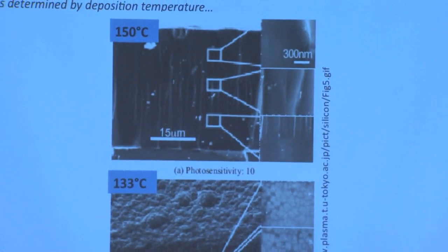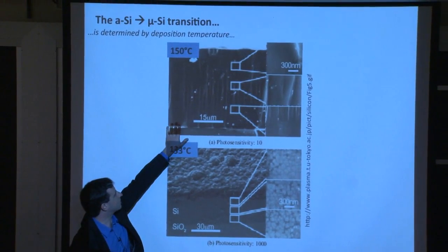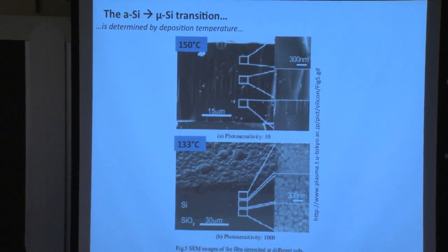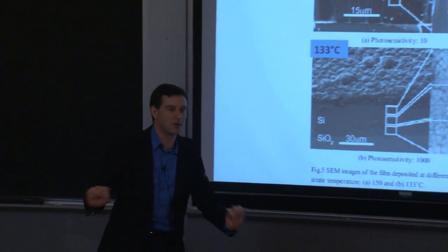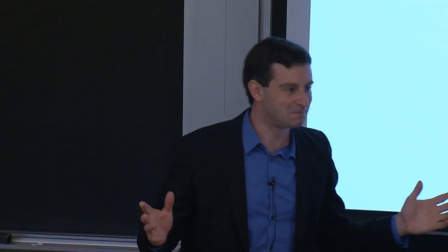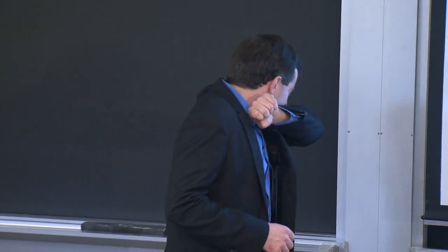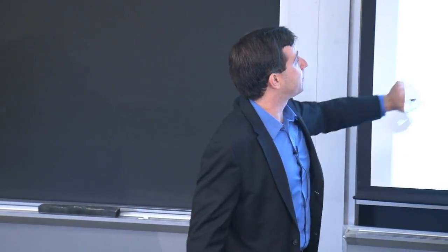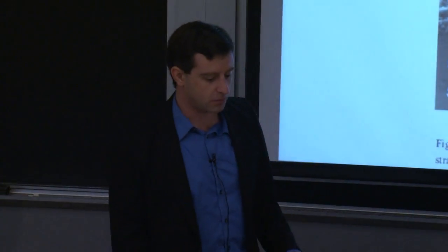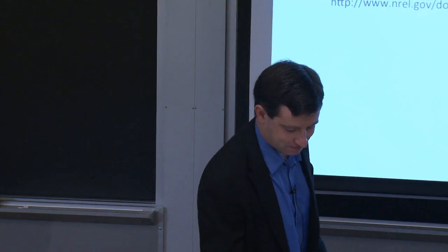And so it's very tricky to nail the deposition conditions just right. Somebody along the way figured out, well, wait a second, we can actually use this microcrystalline silicon to our advantage and stack a layer of microcrystalline silicon on the bottom, put a layer of amorphous silicon on the top, and that was called micromorph technology as a result. And there are companies that have commercialized micromorph. Excuse me. Sneeze right there. So the micromorph technology, commercialized by Oerlikon and previously by a company in the United States called Applied Materials. And we'll get to that in a couple of slides as well.